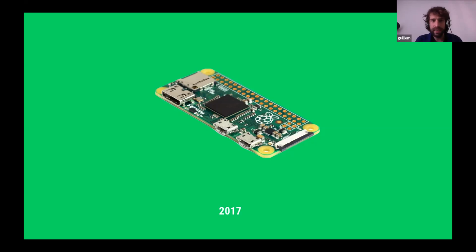So inside this black square you see in the middle of a Raspberry Pi Zero, there's not just a single processor. There's a bunch of components put together. And that's a little bit where we're going right now. In fact, the ESP32 you are playing with these days is a system on a chip, right? It's a bunch of different components: the Wi-Fi module, the Bluetooth module, the memory, the flash drive, and the processor, et cetera, all combined into a single piece of silicon. So in a way, the line between microcontrollers, microprocessors and CPUs is also blurring away. And this Pi Zero is just 5 years old, thanks to this idea of a system on a chip. In a single automated process, you can add so many features into something.